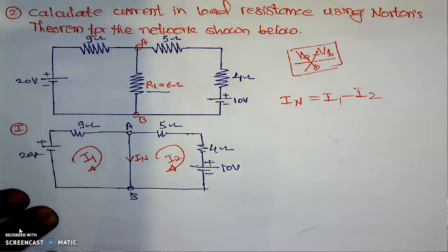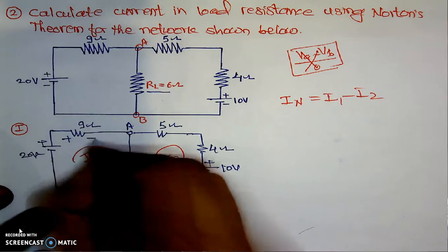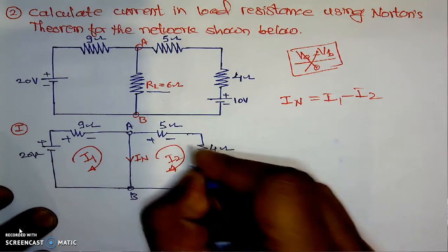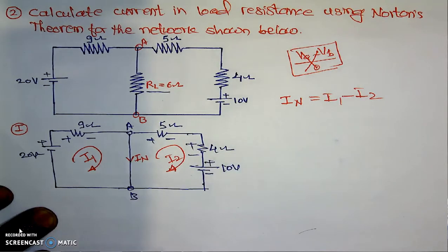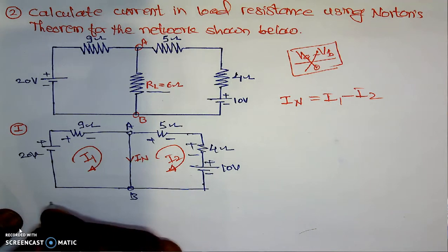We can use direct inspection or mesh analysis, both are the same. Here I will use the mesh because I used the direct inspection method many times. This is clockwise, plus and minus. This is again clockwise. This will be plus, this is minus, this is plus minus, and battery terminals are fixed. If I am using the mesh analysis, we apply the KVL to loop number 1.